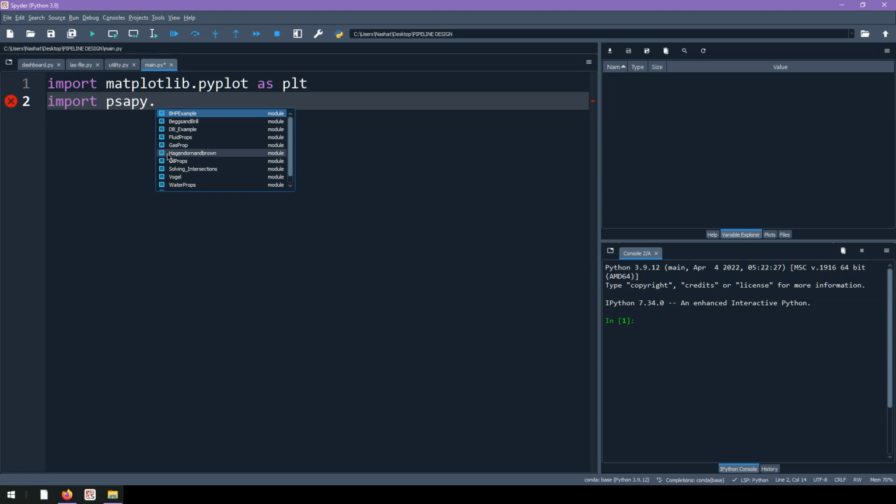By the way, if you are not familiar with these two, they used to be some of the most famous correlations. Beggs-Brill is used on almost all angles. It's preferably used on horizontal pipe sections. Hagedorn-Brown is recommended for vertical pipelines, or actually they are recommended for wells. For this example, we will use Beggs-Brill.